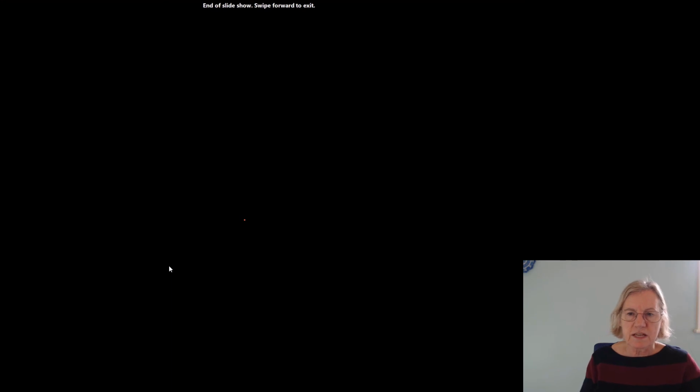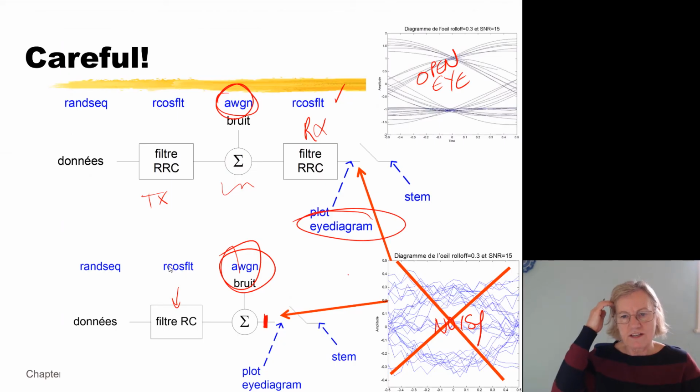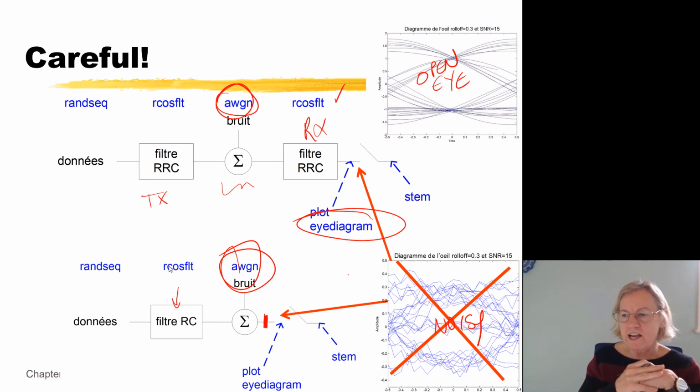Okay, so that covers the root raised cosine pulse shaping. So we put it in the context of Nyquist shaping in general. Went specifically to root raised cosine, very practical, good trade-off, used often, very extensively. And in a homework assignment, you will be manipulating different raised cosine pulses. You will be looking at the effect of different roll-off factors.